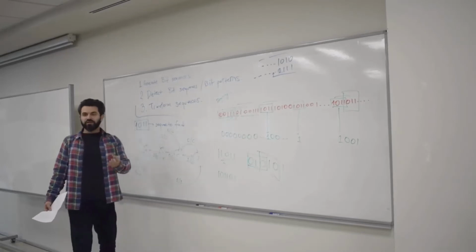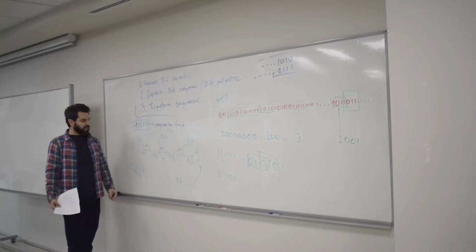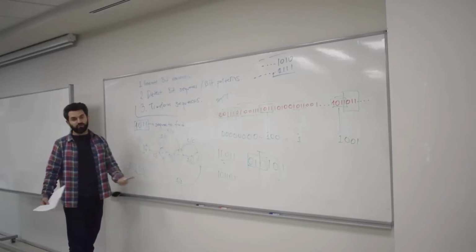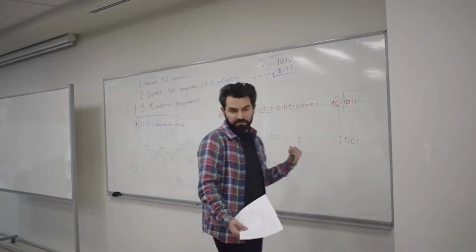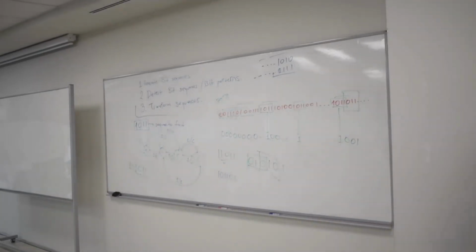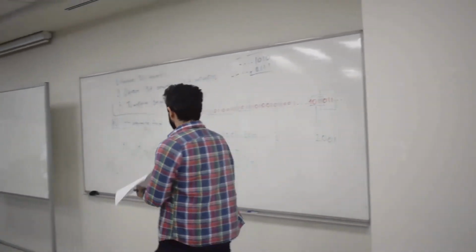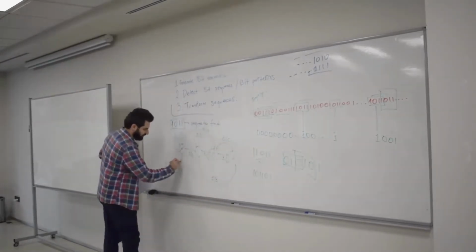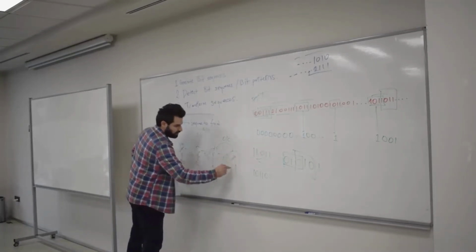So here is the gist of the main message: you cannot reduce the number of states from 4 to any lower number, unfortunately. That's why I'm going to skip the reduction step, because this is already optimal. I'm now going to do the state assignment, which I can already do here by assigning, as I said before, conventionally 0 0, 0 1, 1 0, and 1 1.